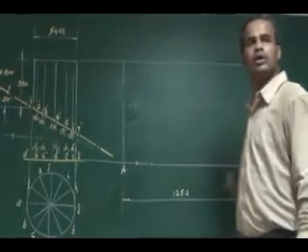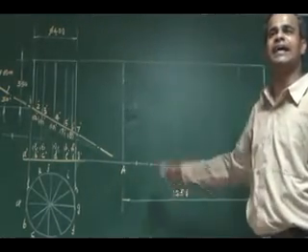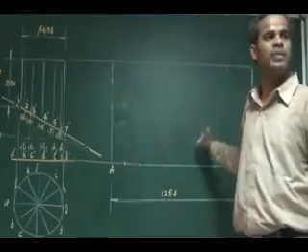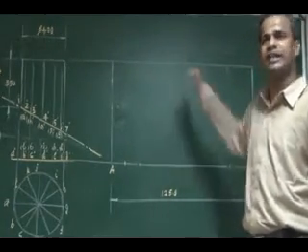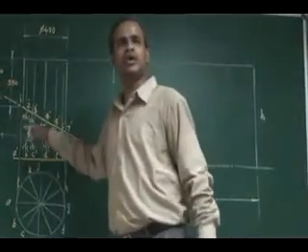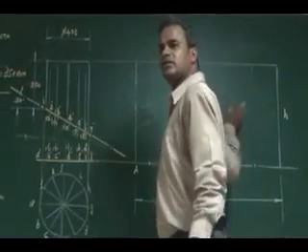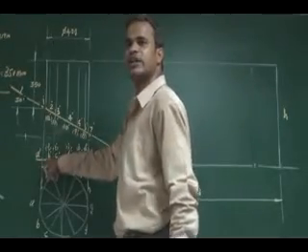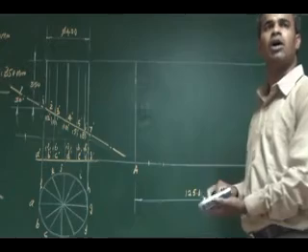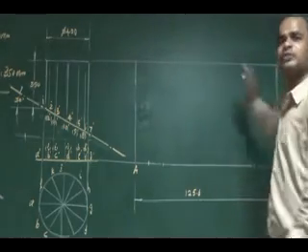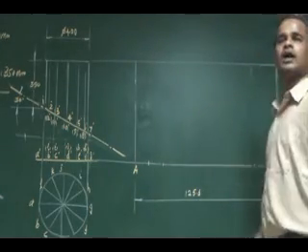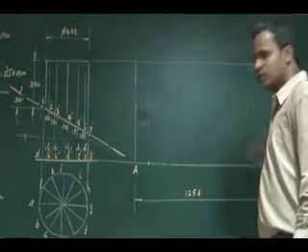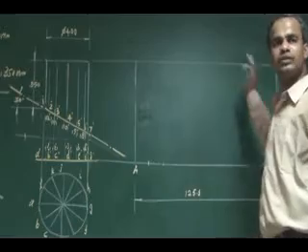And neatly you mark the 12 generators and try to show the 12 generators in your development in 2H pencil. It should not be a dark one. In 2H pencil you try to show the generators also. Then as usual you know how to mark this cutting point. Okay, straight away I can project it. Cutting point 1 is on generator A. I can straight away project it, and mark the cutting points on the corresponding generator. Then you join the cutting points in a sequence with a curve. Then you can show the retained portion.